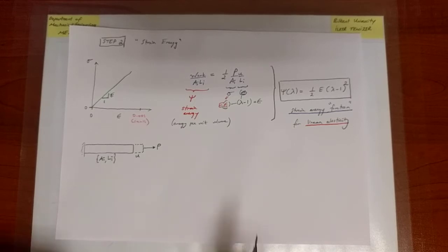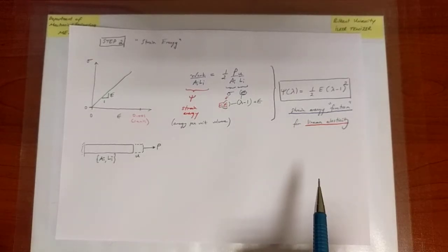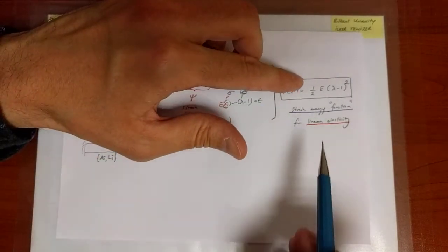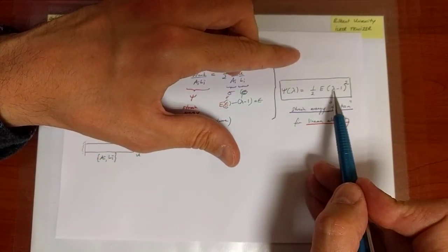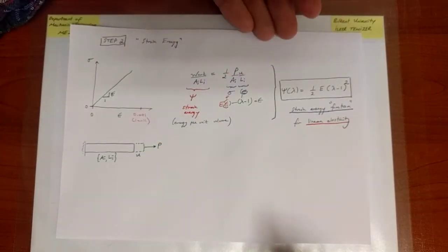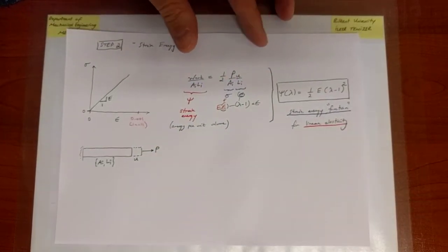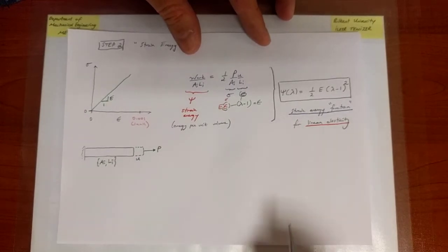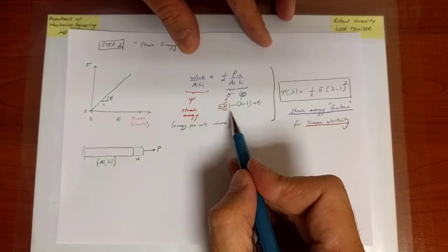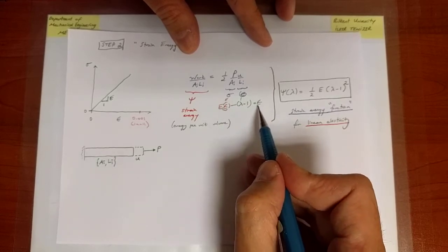So in this case, the strain energy function allows us to deduce the amount of energy that is stored per unit volume of the material when we plug in a certain amount of deformation that is measured in terms of the stretch. So as such, it is something that is very fundamental to the material, because the deformation is expressed in terms of some quantity that is inherently related to strain.